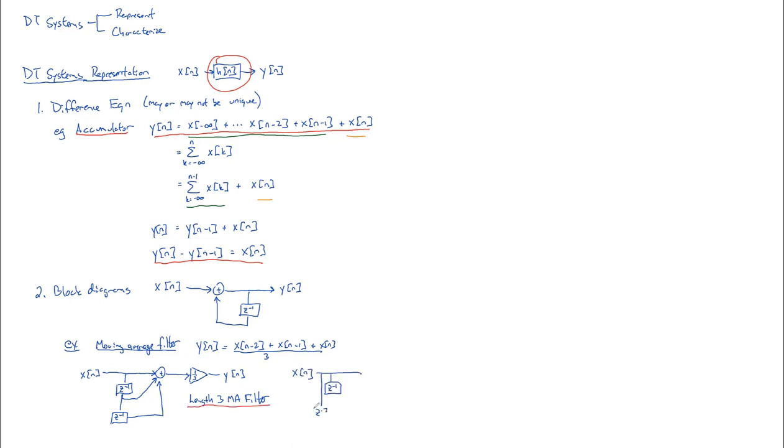You could equivalently, sure. Is this your question? Couldn't you do this as well? Yeah, that's perfectly correct. It's just a little bit more complicated to draw. And the one on the left tends to be the way you'd actually program it on a chip. You'd end up having a buffer, a first in, first out buffer, just a shift register. And you can almost see it's going to be a length 2 shift register with 2 taps on it. But there's nothing wrong with this either.